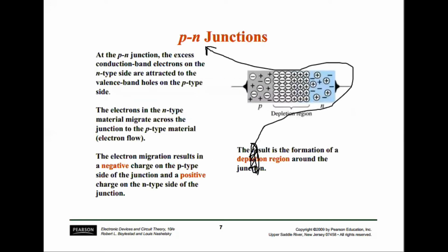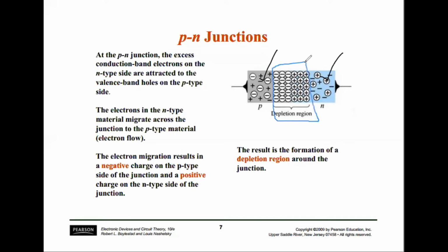The PN junction is shown again here. When we are making a diode, we will have an n-type material and a p-type material. We have two types of materials, and what is this? This is a region which is called a depletion region or PN junction. Why is it called a depletion region? Because it is depleted of the free charges.